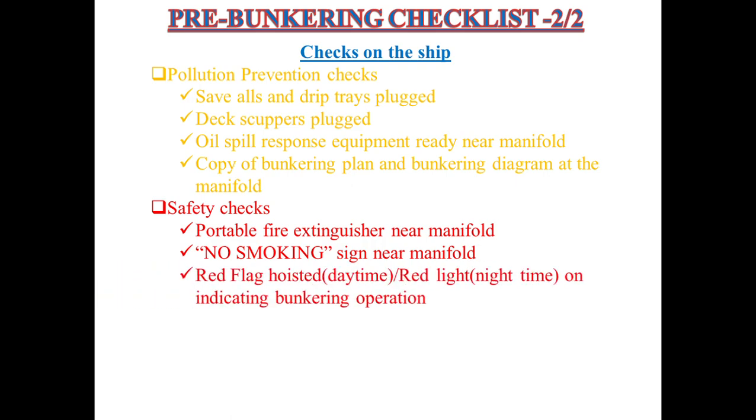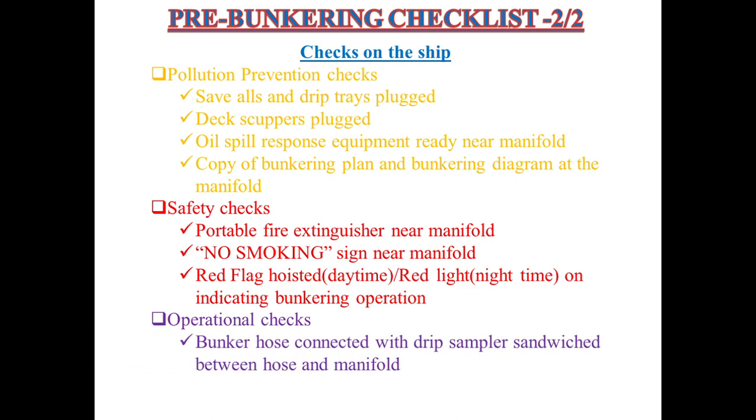We do have a red flag hoisted in daytime, and a red light at nighttime turned on, indicating bunkering operation is going on. We have operational checks, that is the bunker hose connected with a drip sampler sandwiched between the hose and manifold. Then we have bunker valves lined up, manifold valves open.